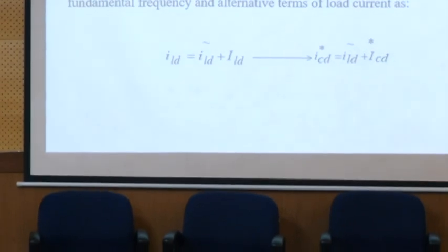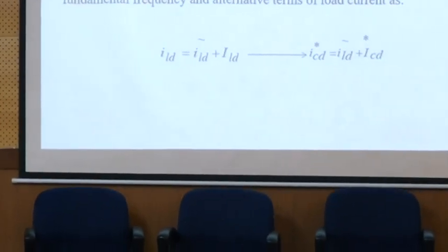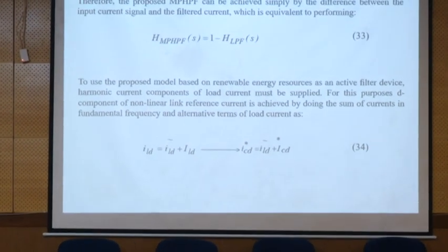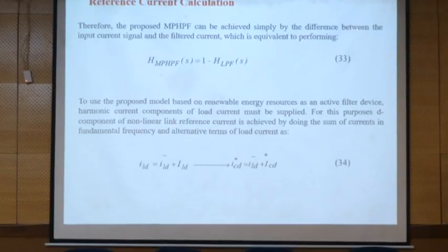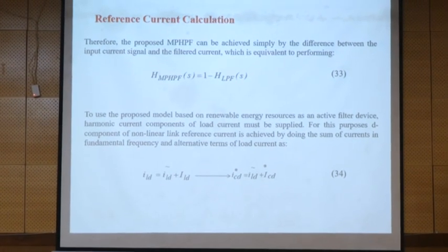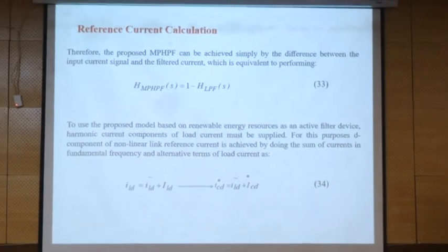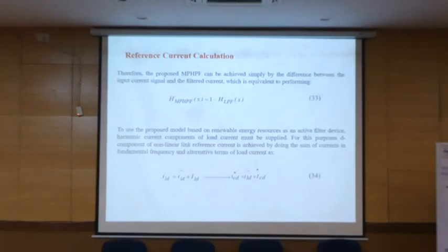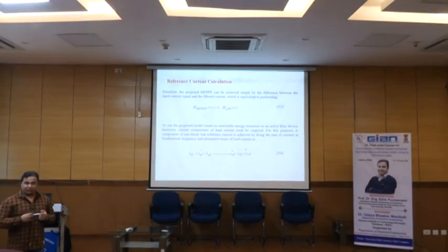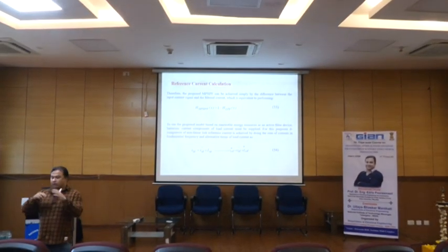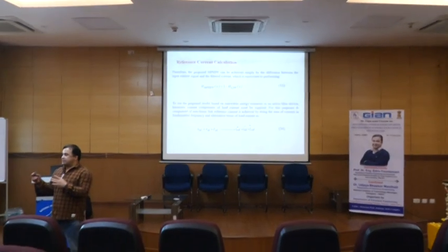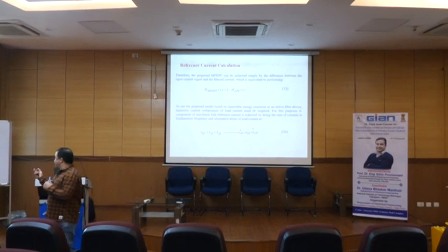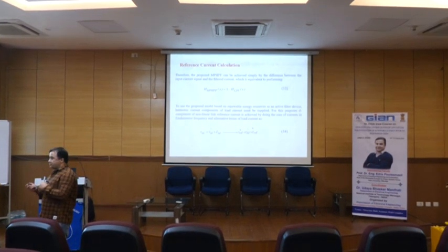So now we go to the active power. Now we talk about the main idea, that we inject the maximum active power. So assuming that you have a nonlinear active load, it is a combination of harmonic frequency and fundamental frequency. This harmonic current takes 60% of the power which can be injected from the converter to the grid.